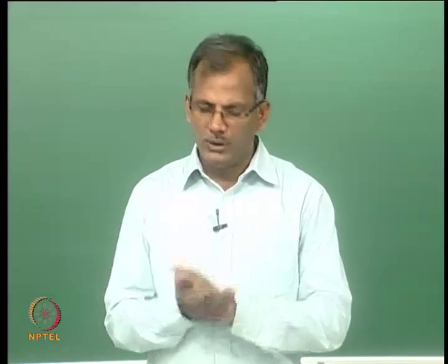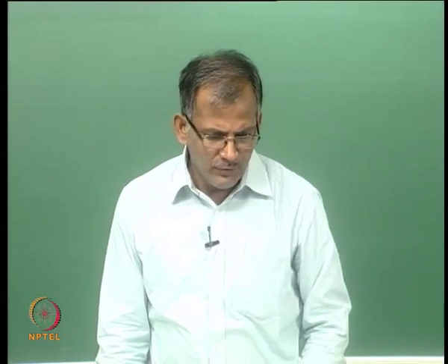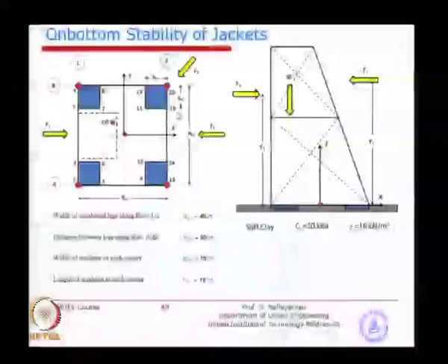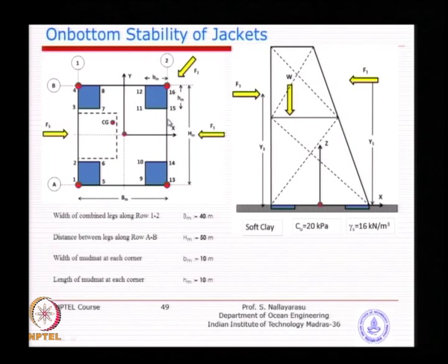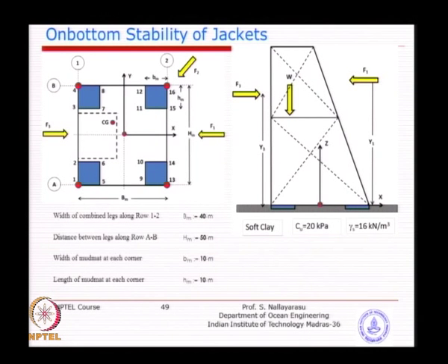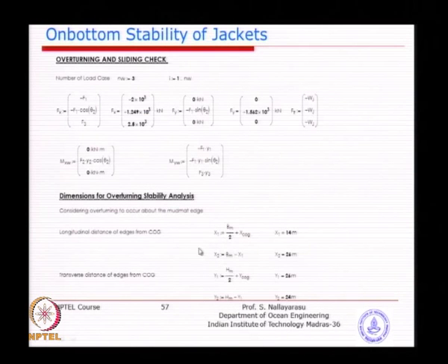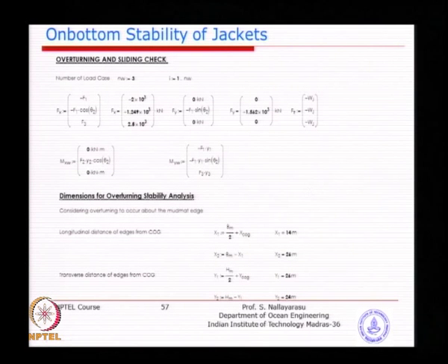So, that is the calculation that we are looking at, and if you want to find out rotational instability with respect to F3, you will find out the distance from this COG to grid number 2, which is 20 meter plus 6 meter. So somehow you have to automate the whole procedure. We are trying to find out the distances, 14 meter or 26 meter, or either way, all 4 phases: phase 1, phase 2, phase 3, phase 4, with respect to the COG, what is the distance, so that the multiplication can automatically be done.